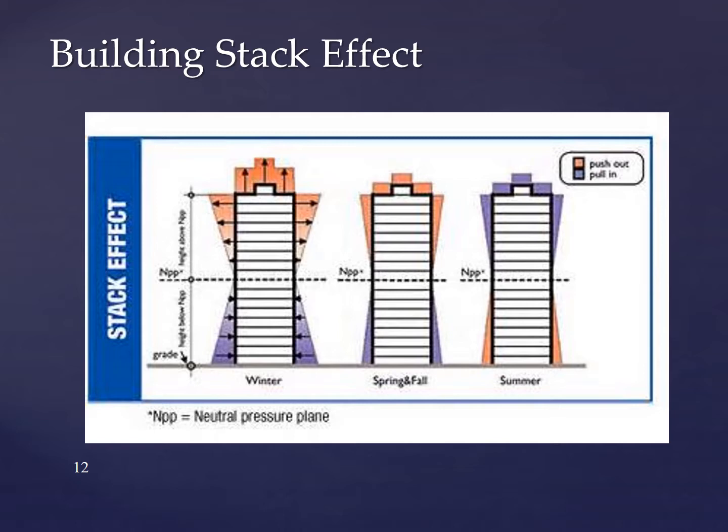And depending upon where you live around the country, you'll find that your stack effect is even more significant or less significant. The only other thing to point out with this drawing is that the effect is magnified at the bottom and at the top of your buildings, depending upon how tall your building is. So basically, the taller your building, the more stack effect, versus the shorter your building, the less stack effect. So it's something that we don't often think about, but it definitely changes and has an impact on the way air flows in our buildings.